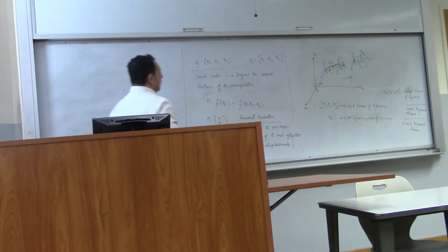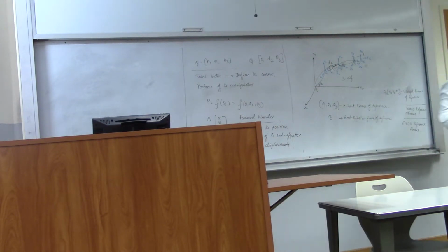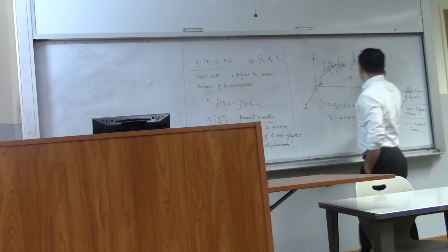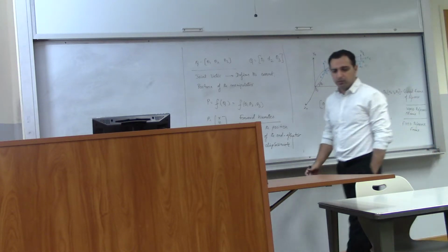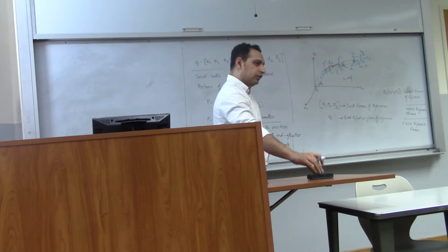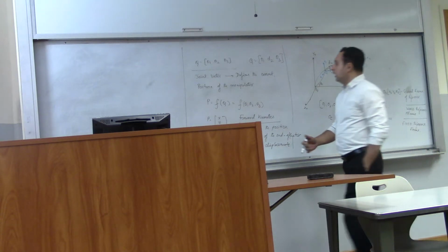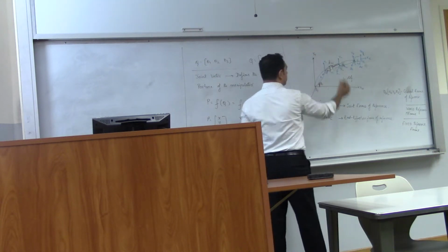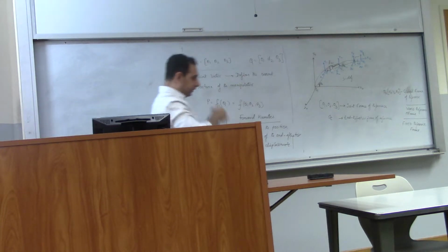Okay. The inverse problem, what is the inverse problem of this? What is the inverse of forward kinematics? The inverse problem is, I want to get to this point. What should be my joint displacements? Which is a very realistic problem. You have a robot fixed, you have a workpiece here, you want to inspect the workpiece or you want to get into a particular orientation to pick it up, and you should know how to displace these angles, what joint displacements should be created to get to that point, because otherwise you won't be able to operate it properly.